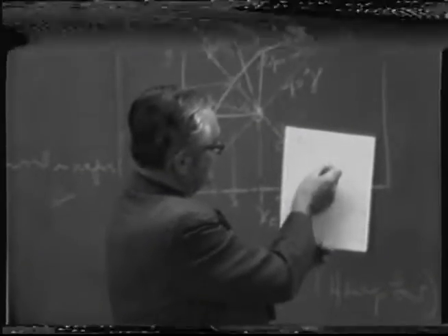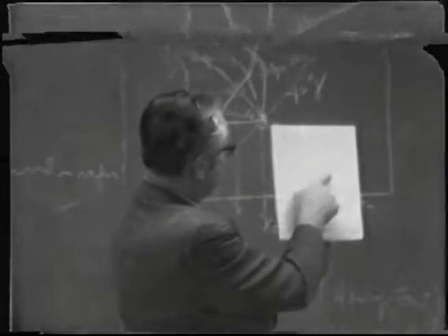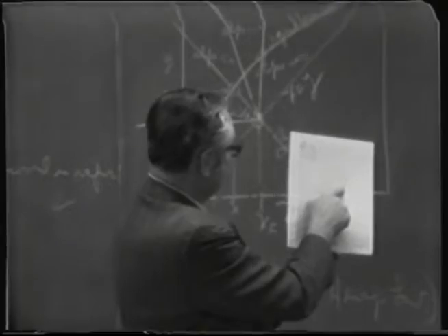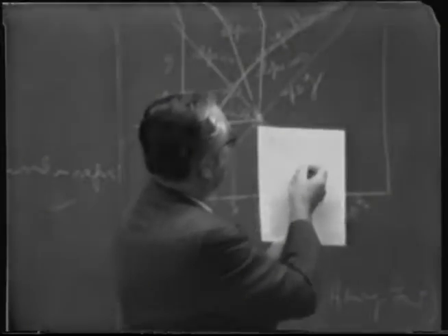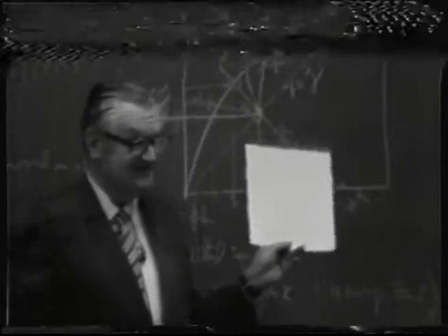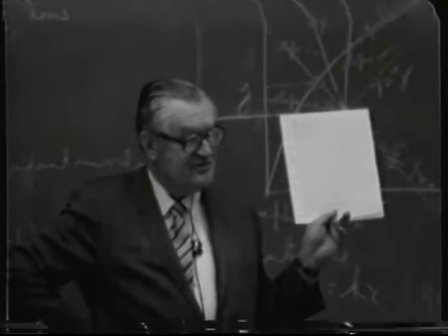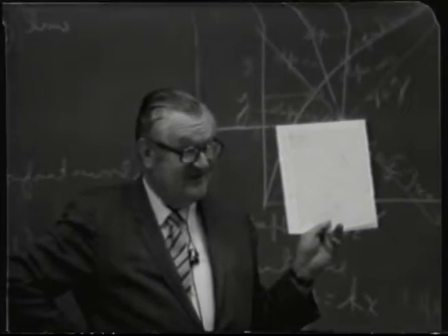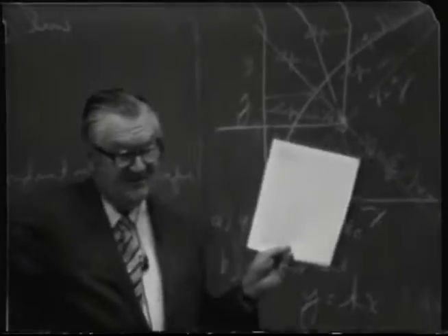These are operating lines. Here, f equal to 0.25, the slope would be minus 0.75 divided by 0.25, or minus 3. So here's a line of slope minus 3. And you simply read off the values of y and x where it intersects the curve. Simple as that. The equilibrium curve is the curve we already have here. I haven't given you any plotted curve on a mass basis. I gave you only the data, so you'll have to plot your own.